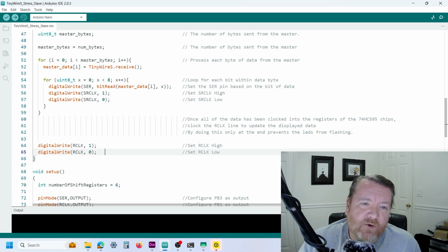We want to make sure that with all 8 LEDs on, we don't exceed the maximum capability of the chipset. That comes down to what 7-segment display and resistor you're using, but it's something to be aware of. You always have to think about the worst case: the maximum amount of current that's going to be drawn by the display with everything on.